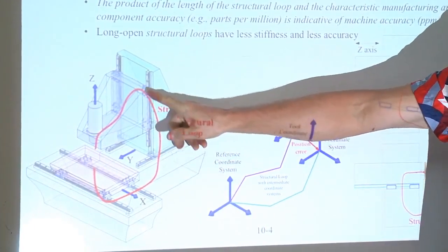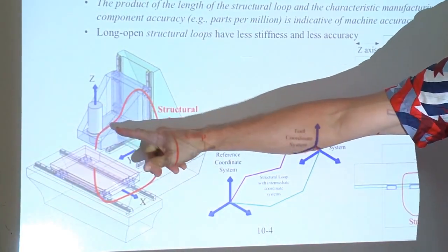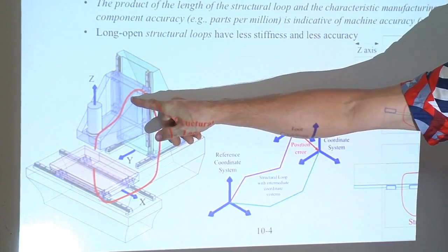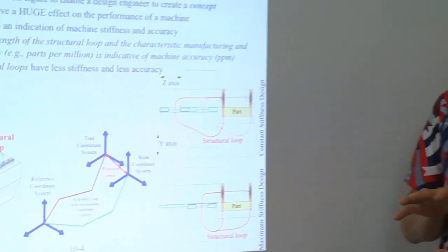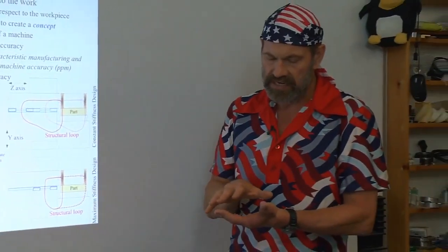Where you have here, for example, you can see 4 bearings, it's passing through the center of stiffness of the bearings. When you have not yet designed the machine, what you do have is an idea of the work volume of the machine. So you can draw that as a cube, and then using St. Venant's principle, be thinking about, well, how much outside of the cube do I have to be in order to contain an assortment of bearings that will be able to move through the motions of the cube.